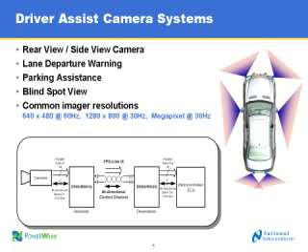And then going across the link, FPD-Link III, we have the forward channel data and the bidirectional control data. This is I2C. And the deserializer takes the video data and forwards it to the microcontroller. The microcontroller in turn is sending I2C commands back and forth with the camera over this virtual bidirectional control link.